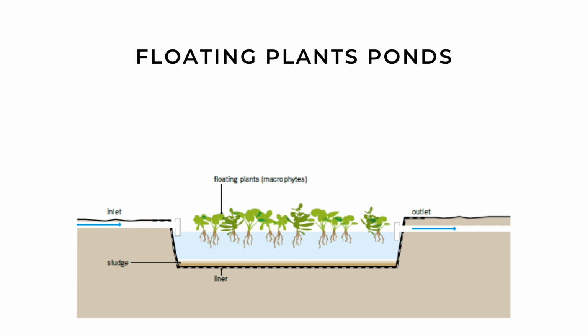To maximize the production of algae, a totally aerobic environment is required, which is accomplished with shallow ponds of less than 1 meter depth. It is a common practice to design these ponds in the shape of a carousel, similar to an oxidation ditch. This technology is particularly interesting for reuse as it generates valuable other products.